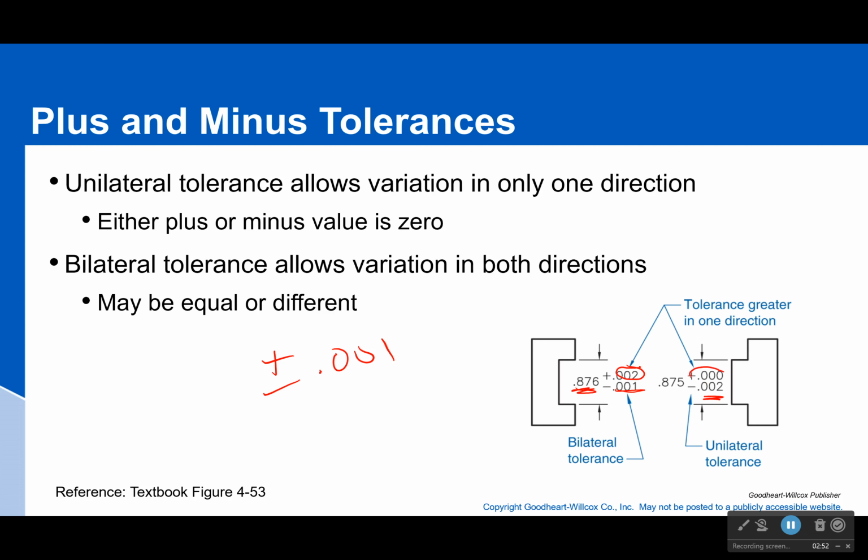And this does happen. There are cases where you, under no circumstance, can be bigger, but you can make it smaller, which for this feature at least would be fine. Because if they made it too big, they could always just trim it down. That's the nice thing. Usually for holes, a bigger hole is still typically fine because usually you get increased tolerance. And for pegs, a smaller peg is usually fine when it comes to making things together. So in most cases, there's a way to fix things. And that's actually going to bring us back to our max material condition a little bit later. I'm not going to talk about that today, but that will come in fairly soon.